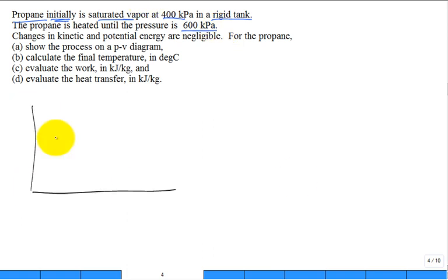So let's put up a generic pressure-volume diagram. Put P on the y-axis, V on the x-axis. We know that it's pretty steep, gets up to a point, and then it kicks way over. But people could draw it symmetric, it'd be okay. What's at the top of this PV diagram? CP, the critical point. Every state coming down on the right side is a state of saturated vapor. Every point coming off on the left, on this line of the dome, from the critical point on down, is saturated liquid. So we are starting with saturated vapor somewhere along that line.